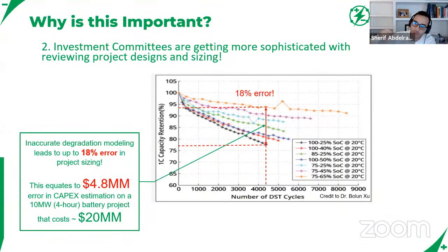So to get an equivalent cycle, you have to do that more times. Overall, it's the same number of cycles, but with one usage profile you're down to about 94%, and with the other, you're down to 77%. That's a big difference, realizing that most battery OEMs will specify the end of life of their systems at around 70%. So it really makes a difference how you dispatch your battery system.